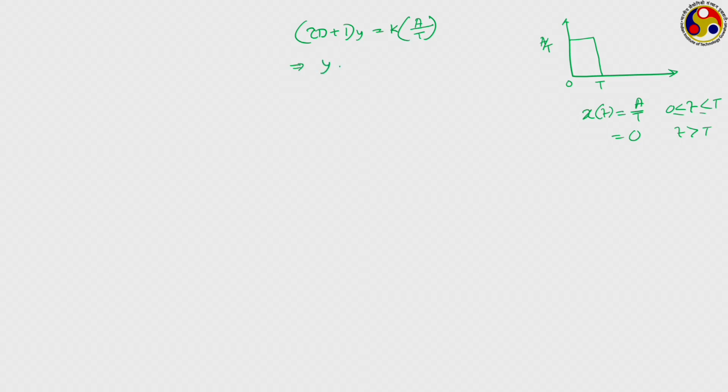So, following this solution, we know that y(t) will be what? Just try to remember what we have already done in our previous lecture. When we solve for this step function using the constant, it will be (K/T) into (1 minus e to the power minus small t by tau). It was just there also a couple of slides back, where K by T is the right-hand side, and we are having the negative exponential inside, tau being the time constant for this.